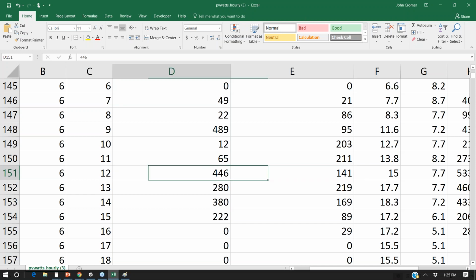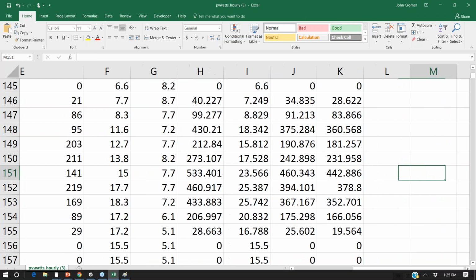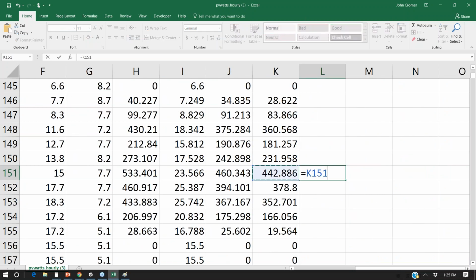Under our sunniest condition, we're producing 440 watts. What I really want to illustrate is, if we divide the 143 watts we get on the pea soup day by the power that we get on the sunny day, on the pea soup day you're still actually producing some power. You're producing not 15% of what you would get on that sunny day. You're producing about one third of what you would get on that sunny day.